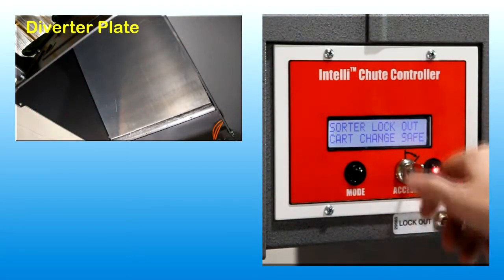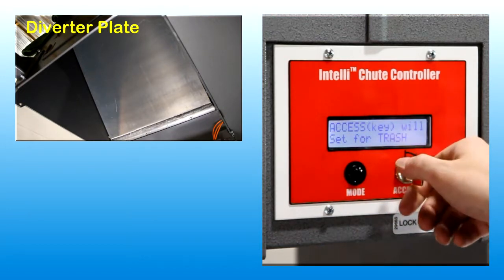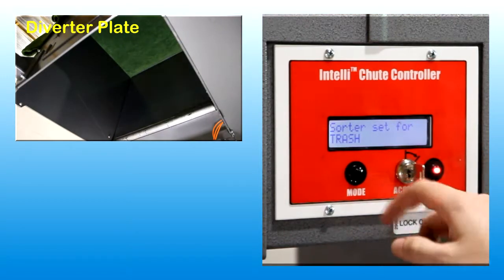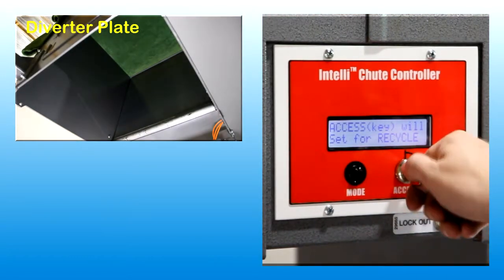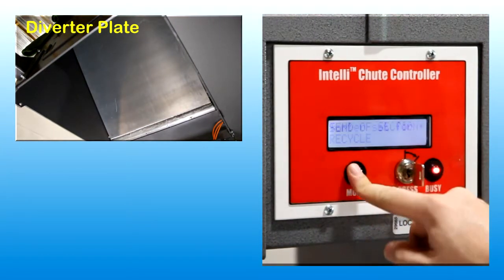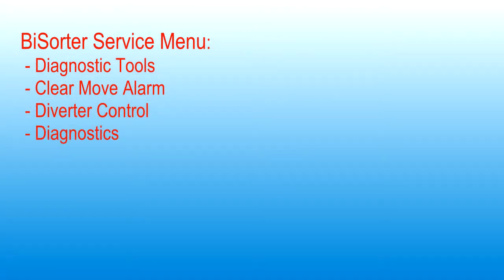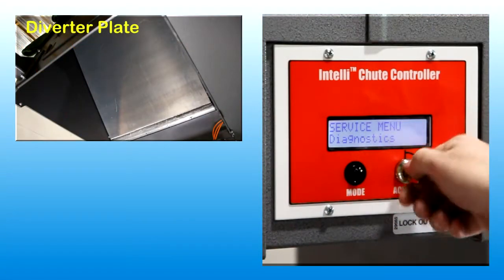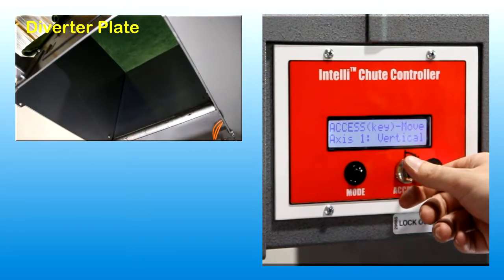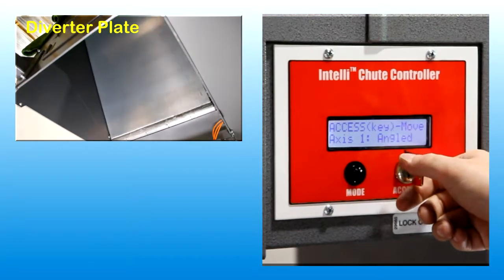Diverter Control menu provides functions to move the diverter plate from one side to the other. Use the Mode button to navigate through the menu options, and follow display prompts to activate specific functions. Diagnostics menu also moves the diverter plate from one side to the other. However, display prompts use mechanical equipment-based descriptions instead of the side name labels.